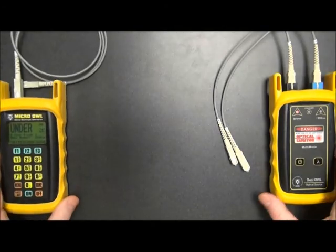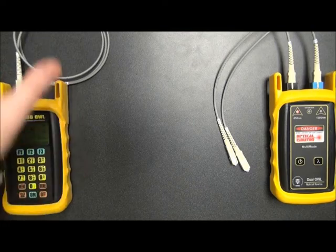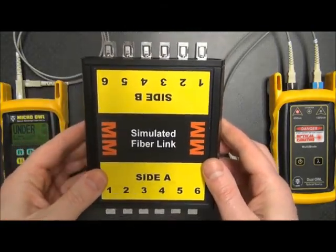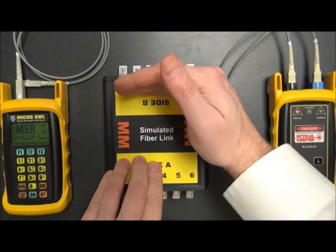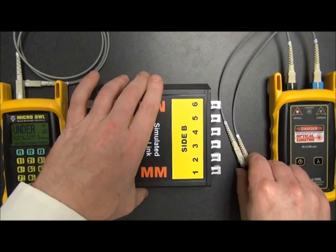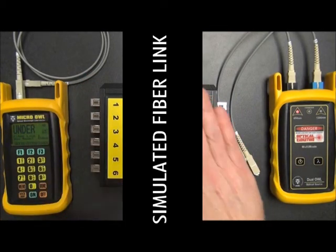Okay, so now each tester is on its own side of the link, and what we can do now is start taking readings. We connect into our link. Now, for convenience sake, I'm going to use this little box here. It's a simulated fiber link. So what we have to do is pretend here that let's say side B is one side of the link and side A is the other side of the link. Okay, so I'm going to demonstrate that here. So the light source is on side B, power meter is on side A.